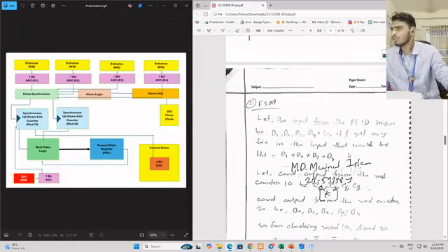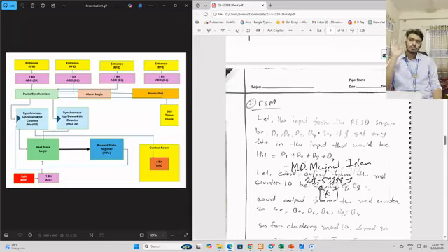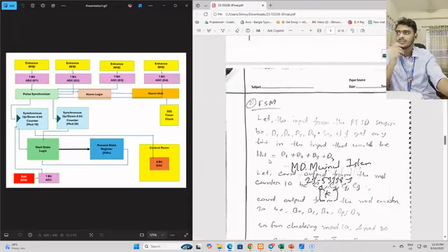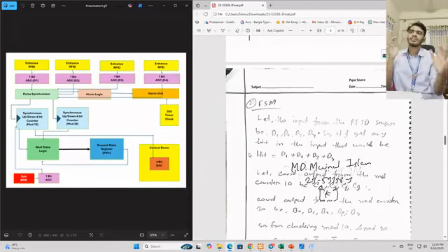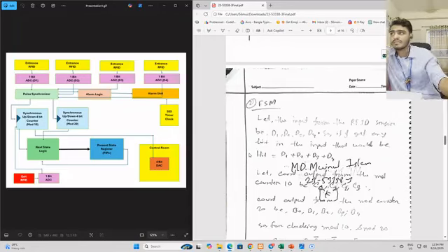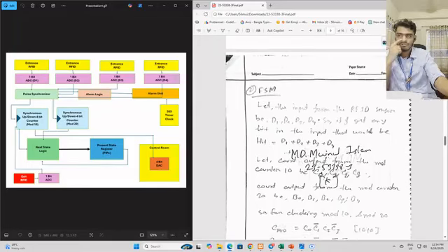Next, let's go through the FSM, finite state machine. For that we have simplified some things, such as the hit. How can we detect an entry, that someone is entering? We can detect it by a hit. How is a hit calculated? If any of these ADC sensors, any of these ADC blocks, gets a high pulse, that means someone is trying to enter, right? So if we OR these signals, we can get a hit. We can rely on that: if hit goes high, that means someone is trying to enter.